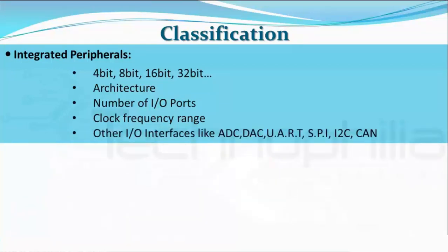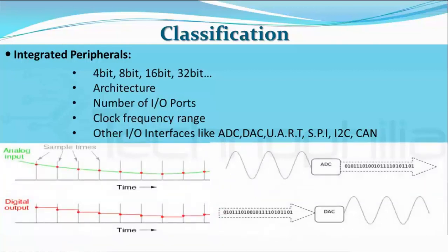Nowadays in the modern controllers you will get a number of advanced I/O interfaces, using which you can connect varieties of devices and modules in your project. The basic one is ADC, or analog to digital converter. As your controller is a digital device, it cannot directly process analog quantities like sound, temperature etc., so you have to select a microcontroller which will have an inbuilt ADC feature.